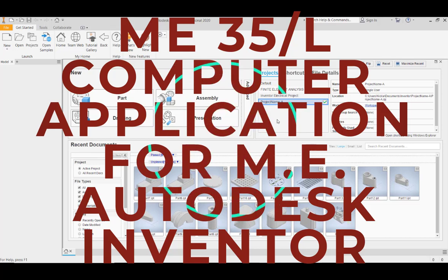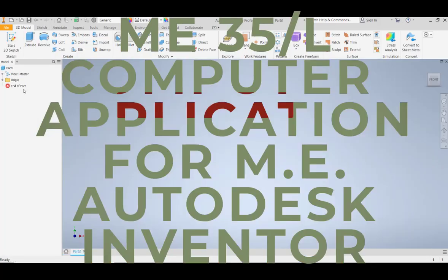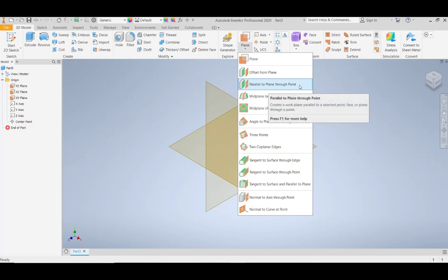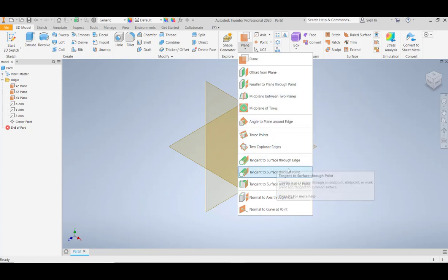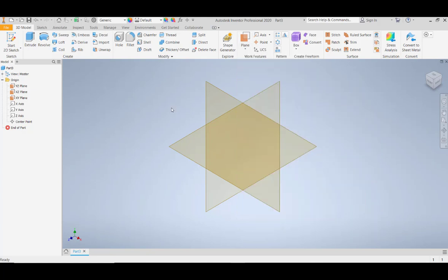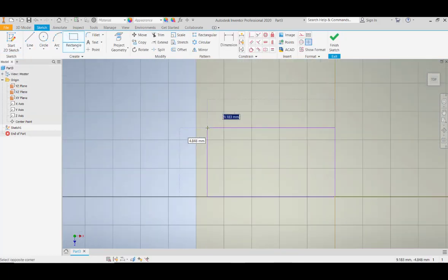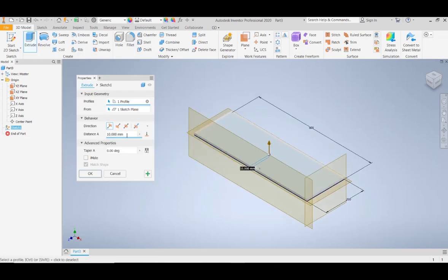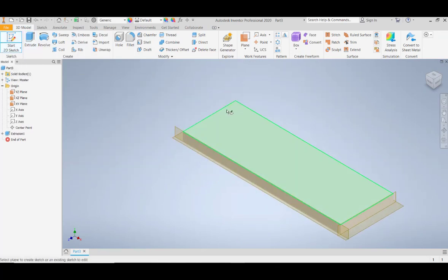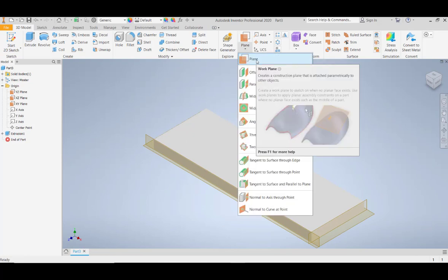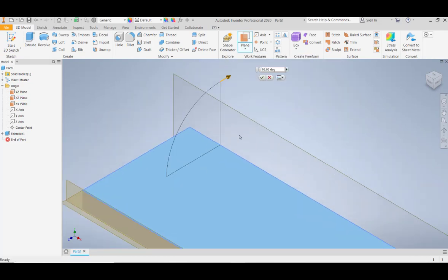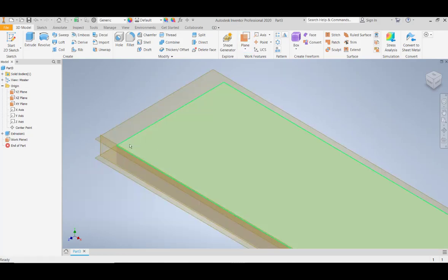You developed basic models in the previous chapters by extruding or revolving designs. All of those models were made on a single sketch plane, which was either the XY, YZ, or XZ plane. Most mechanical designs, on the other hand, are made up of a combination of sketch features, reference geometries, and solid features. To make a model, all these features are combined. The majority of these features are distributed across multiple planes.